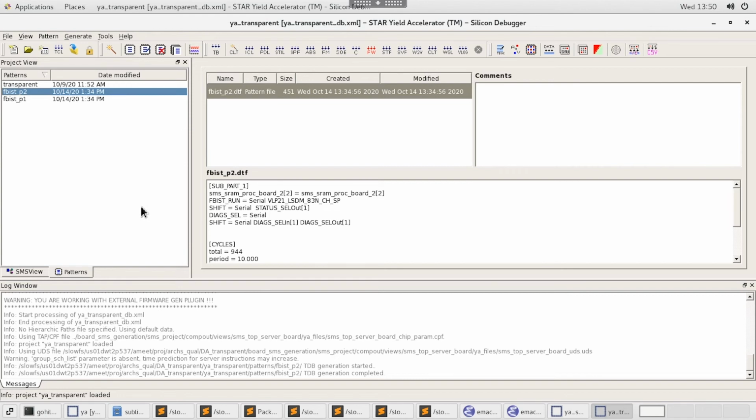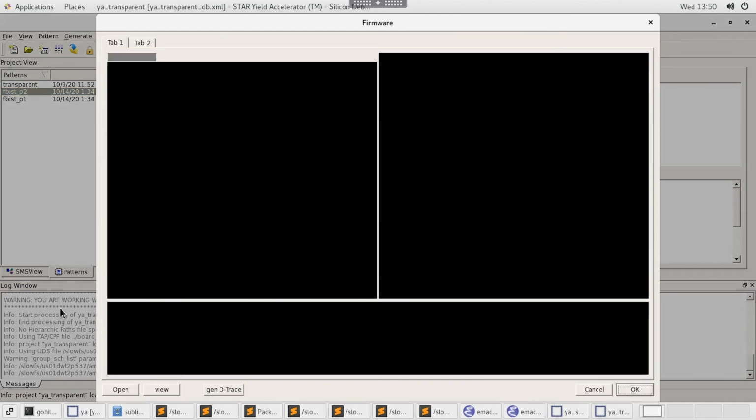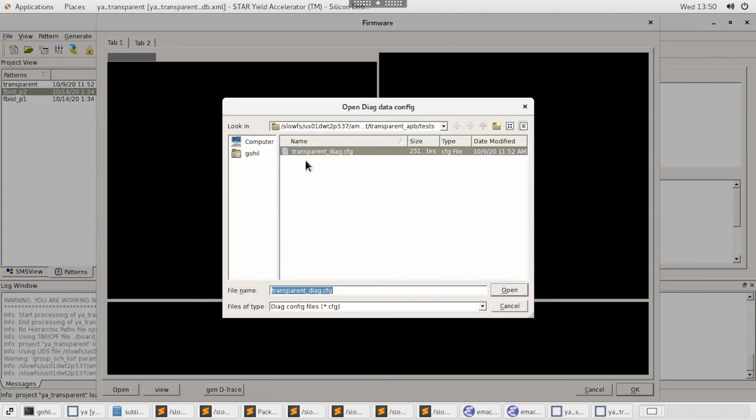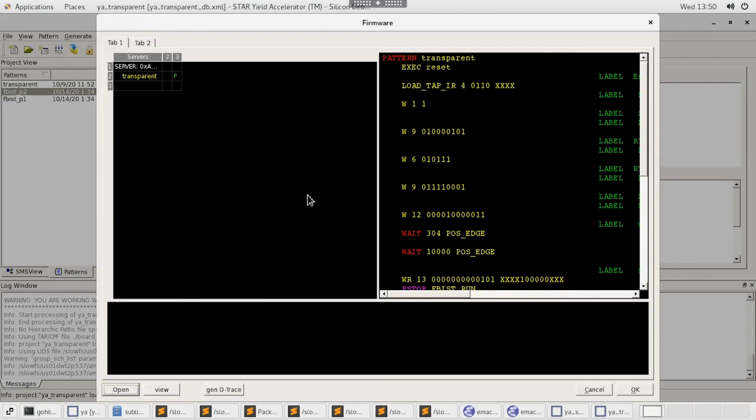You or your team will need to fill in some code to enable and run the MCU timers and set up a way to dump the diagnostics array into a file. Once these functions are defined, you can run the firmware and see the results in the YA diagnostics view.